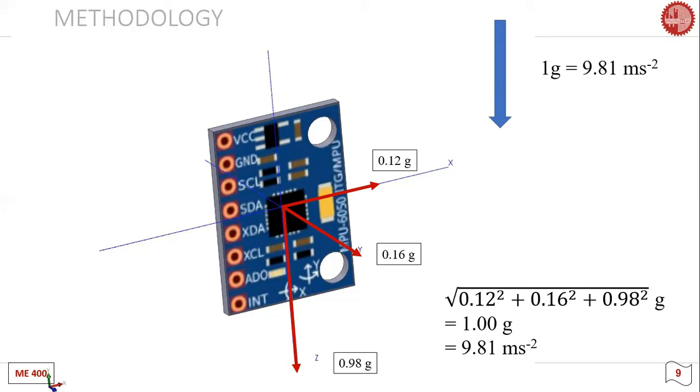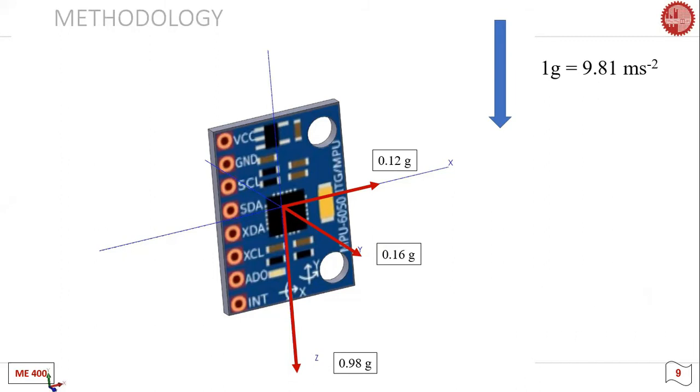If the sensor is randomly oriented like this inside an elevator, when the elevator starts moving vertically, it will pick up the vertical acceleration of the elevator in all three directions. Therefore, we cannot distinguish the lateral acceleration and vibrations with this orientation.